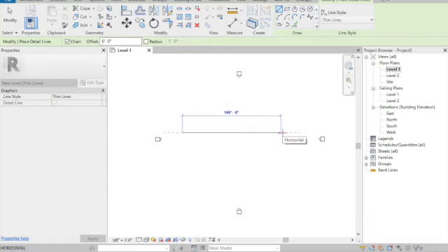Press Escape after you've clicked to end drawing any more lines. Note, if this chain box is checked, Revit will begin drawing a new line at the endpoint of the previous line. However, don't get this confused with a polyline as AutoCAD will produce. All line segments in Revit report as individuals. There is no polyline function in Revit.